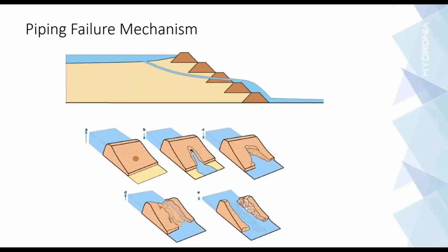So as the water velocity increases, you get more erosion, and the erosion increases the porosity of the material, and as time passes, this porosity is so high that then you get pipes, and that's why they call it piping. So you have these large conduits that communicate the water to the downstream area. And at some point, if this is left uncontrolled, you will get a total failure of the dam itself. So that's very dangerous, even though it's slower in development with respect to the overtopping failure mode. It's a very dangerous failure mode, and it should be at least analyzed in many dam failure risk assessments.